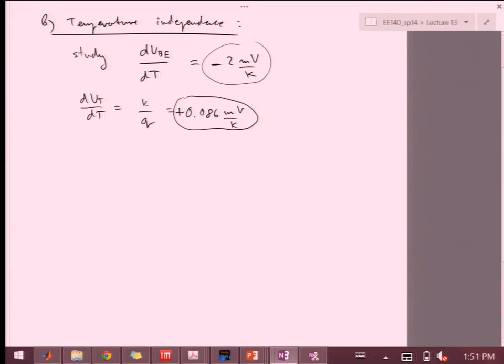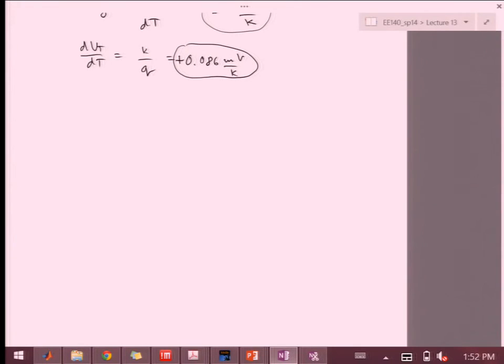So I have two voltages that are naturally occurring in my circuit that have different gradients with respect to temperature. And what a circuit designer does is adjust these two so that when they get summed together, the gradient goes to 0. Okay, so that's the whole story about the temperature-independent reference sources, right? So the way you can do that is, I'll just draw it first conceptually.